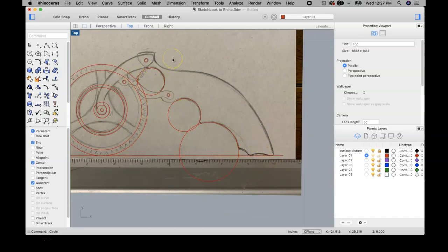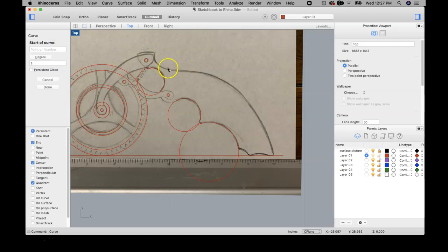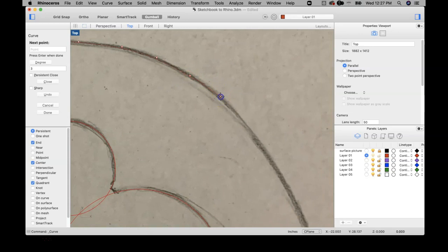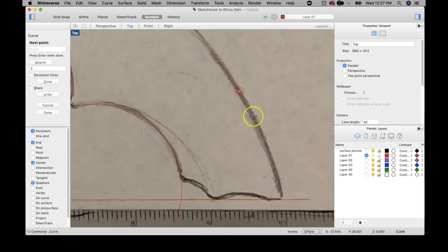Another tool that's very useful in terms of 2D drawing is this icon right here, which says control point curve. I want to just demo this. So if I've got an existing drawing, I can come in and start drawing. We'll just show you in here in the middle of this. I can draw with this, and you do have to be careful. Rhino basically builds curves from points, so it's a series of points, and you'll notice how it smooths the line as I'm placing that.